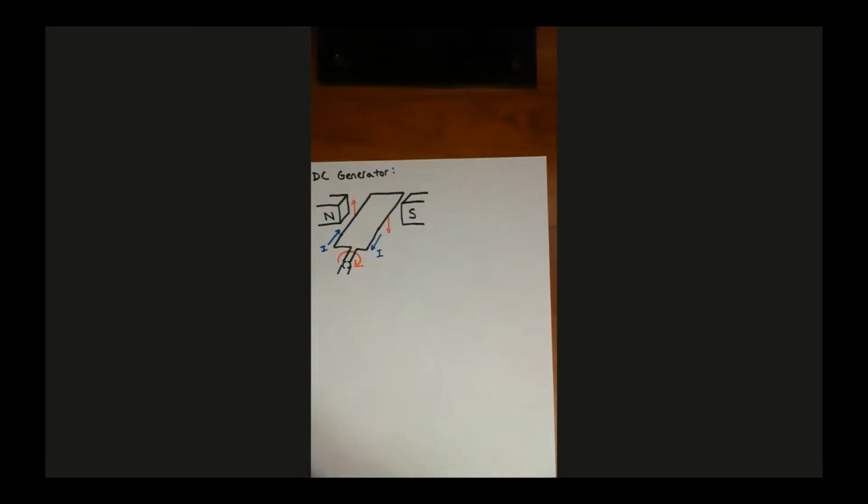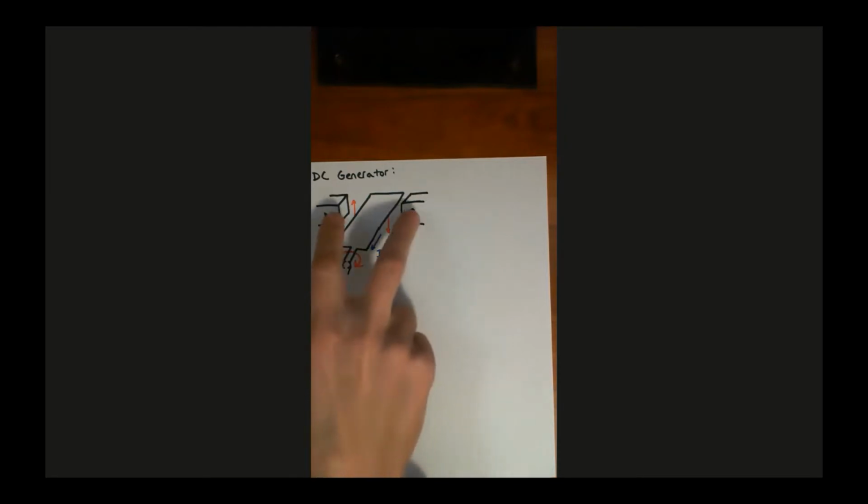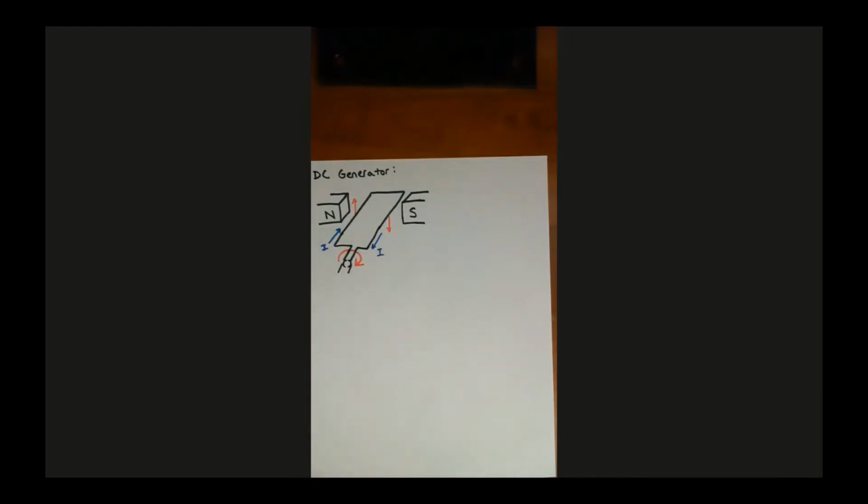So we can see that those two lead to the third. The two being the rotation, the movement, and the magnetic field. If we have those, that leads to an induced voltage, which causes current flowing or flowing charge inside the armature. So the question might be, what if you applied the voltage and got a charge or current flowing inside the armature in the presence of the magnetic field? Would you in turn get motion? You see what I'm saying? We kind of got three different components. We've got motion, we've got flowing charge or current, we've got a magnetic field.